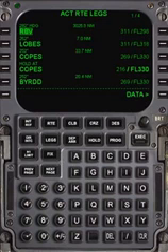The NDB contains all of the information required for building a flight plan, consisting of waypoints, intersections, airways, radio navigation aids including distance measuring equipment (DME), VHF omnidirectional range (VOR), non-directional beacons (NDBs), and instrument landing systems (ILSs).